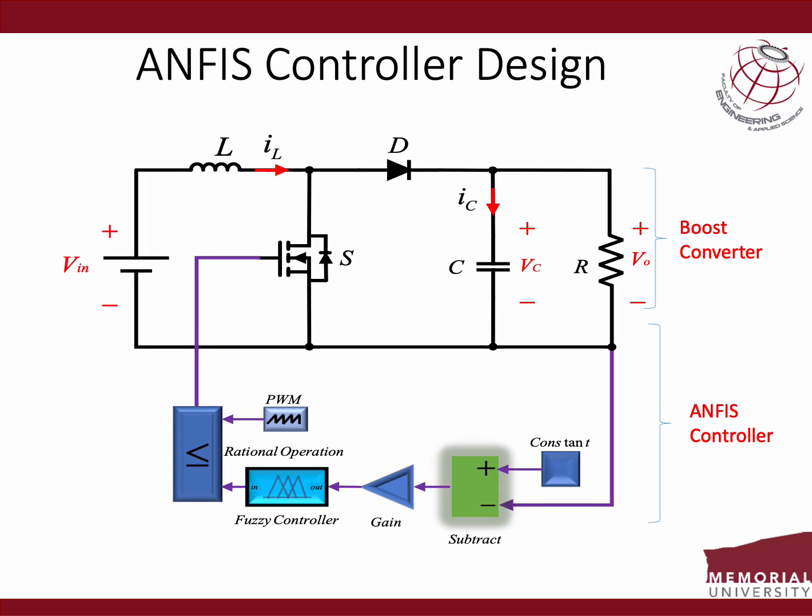For the ANFIS controller, like I said again, we picked information from the PID controller and fed it to the ANFIS. Then we trained the ANFIS using the MATLAB Simulink Fuzzy Logic Designer app to train the controller. By so doing, we're able to optimize the voltage output from this design. And from the simulation results, we will understand how we're able to improve that from all three scenarios.